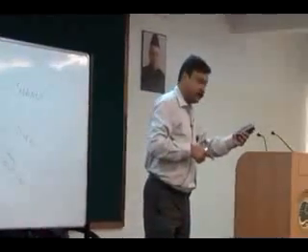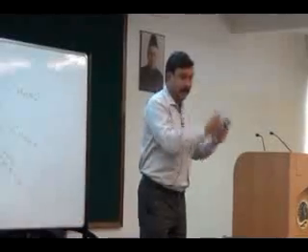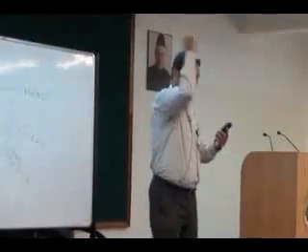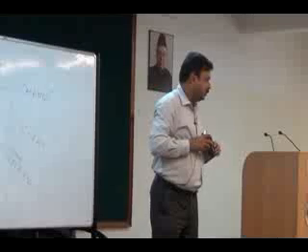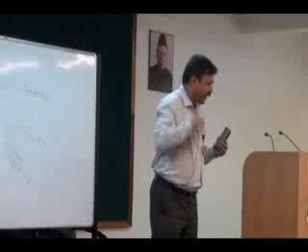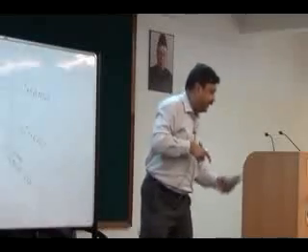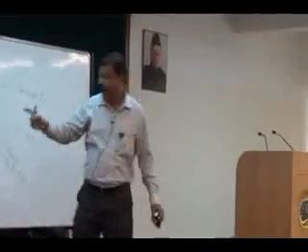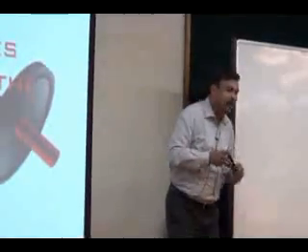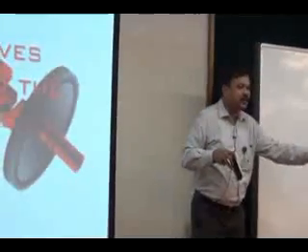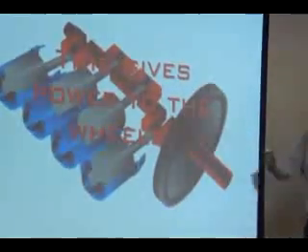During the exhaust stroke, the high pressure burnt gases are to be pushed through the exhaust valve. Will you require energy for that or will you get energy from that? You require energy for that. Where will you get it? Again from the flywheel. You have a huge mass which keeps on rotating. That stores the energy obtained from the power stroke, and that is provided back when the piston needs that. So that is the function of a flywheel.